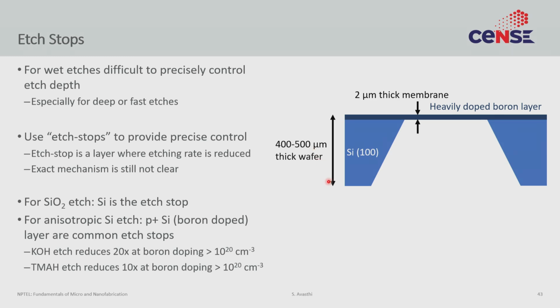So of course, this means in order to go 400 micron, 400 by 6, you need essentially 60 hours. Now, if you are doing an etch of 60 hours, you leave the wafer and walk away, and you come back after 2.5 days.